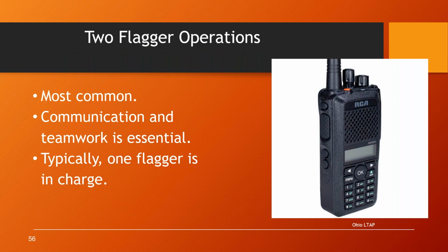The most common flagger setup is the two flagger operation, and so communication between the flaggers is essential. So you either need to be able to see each other and communicate with signals, or have two-way radios, and one flagger is usually in charge.